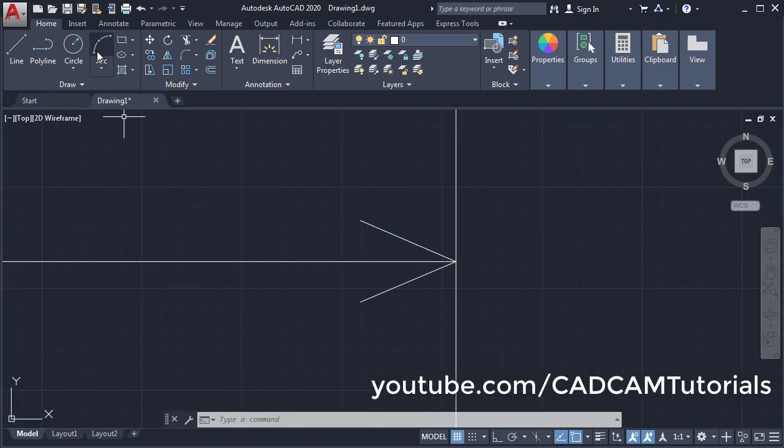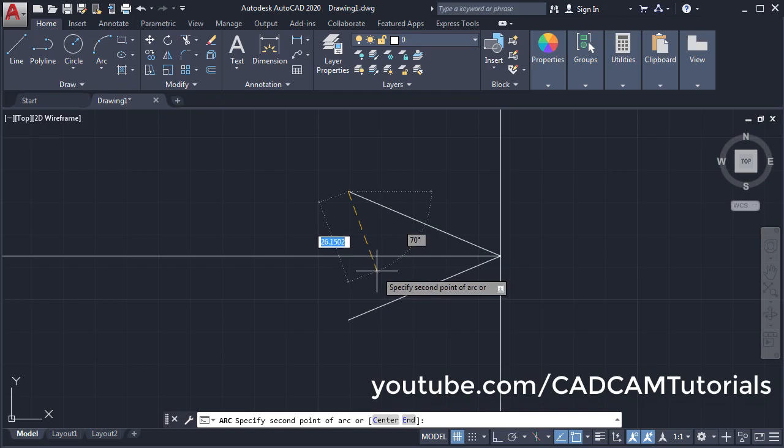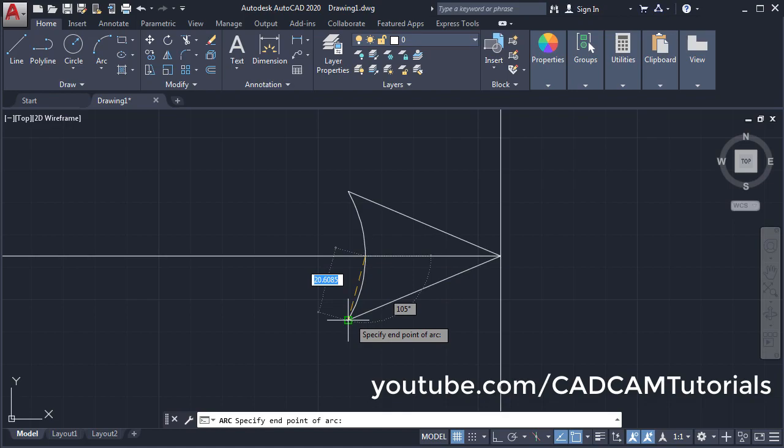Then we will create one arc here. For that click on 3-point arc, specify a first point, then take your cursor to this end point and drag that point, don't click there, take it away and click here, then click on this end point.